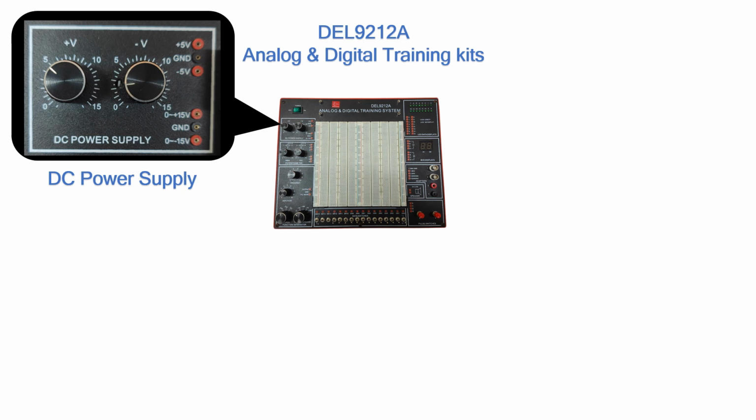In this section, we will see there are 2 sets of power provided. The upper right corner is a set of fixed power consisting of negative 5 volts, 0 volt, and positive 5 volts. And next, the lower right corner is a set of variable power that can be controlled by using 2 different knobs, from 0 until positive 15 volts, or from 0 until negative 15 volts.